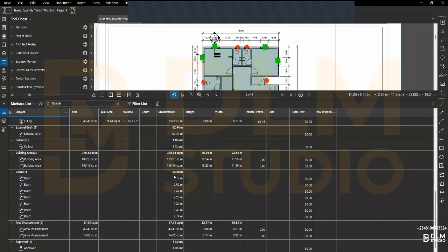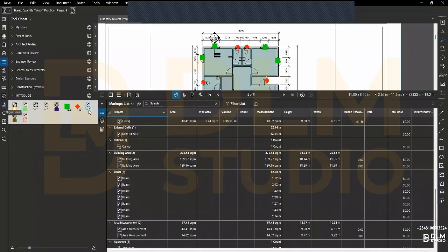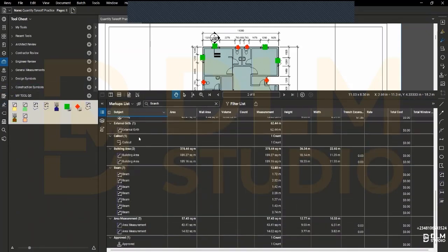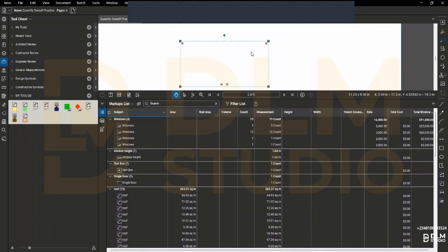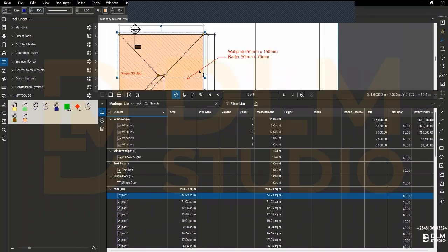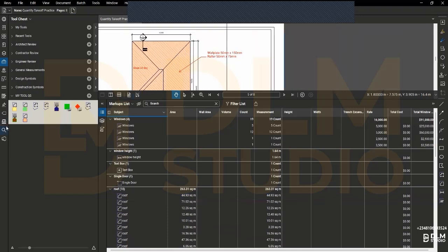Now we don't calculate for the members. Like I said earlier, we don't calculate for the members, just the roof covering alone. That's just for the roof covering. That's what we're measuring. So we only follow the path of the roof itself. So only follow the roof covering slope direction. That's how you measure for the roof covering.